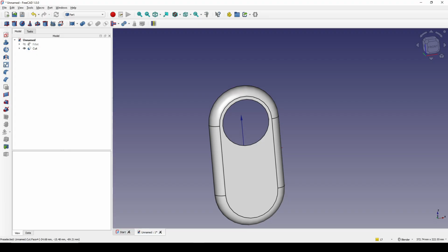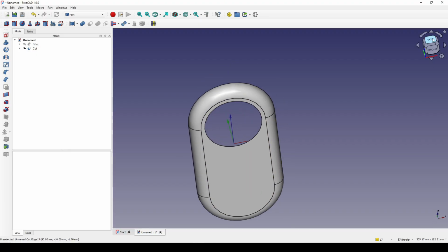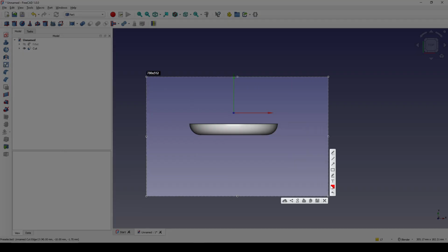So in FreeCAD, what I will do is create a line connecting from the center of the circle to this edge, and another line the same length as this line but offset a little bit to the back. And on these 2 lines, I will generate multiple points in between, like 10 points on this line, and also 10 points on this line. Okay, so we have 10 here and 10 here.